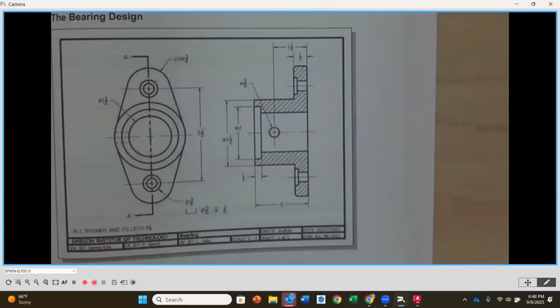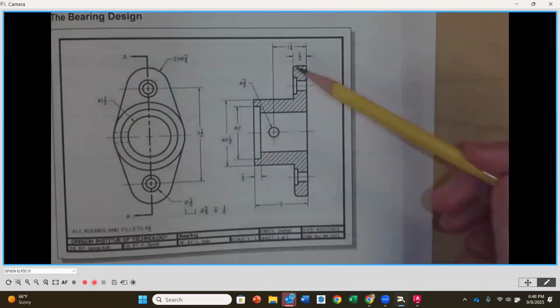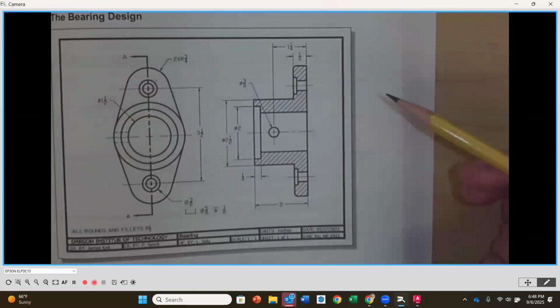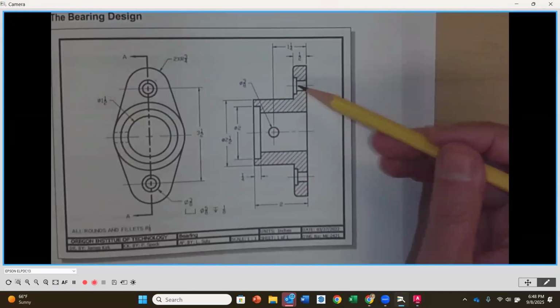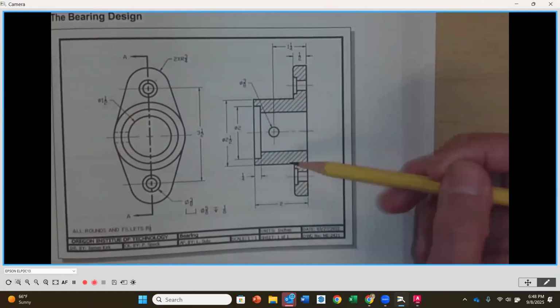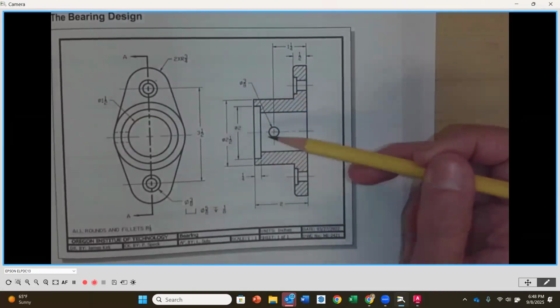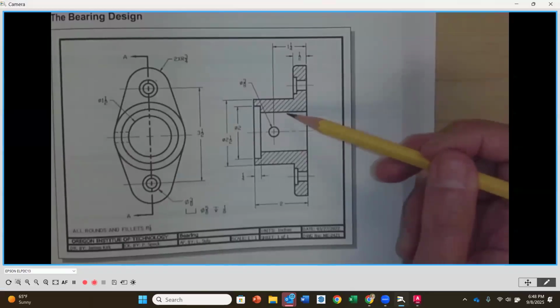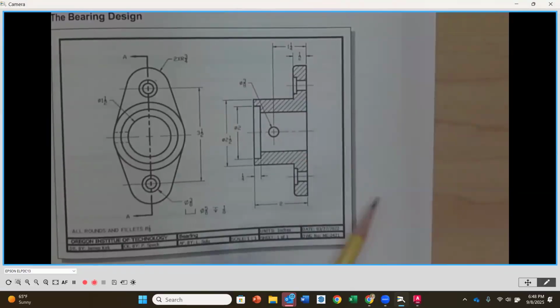So we're literally cutting, sawing this in half. And you're going to notice what that gives us the opportunity for are the clean edges, the object line edges for each one of the elements here. Okay, so let's start. I want to start in the middle here with our little counter bore and then the through hole. So the through hole, these 2 lines right here, they line up.